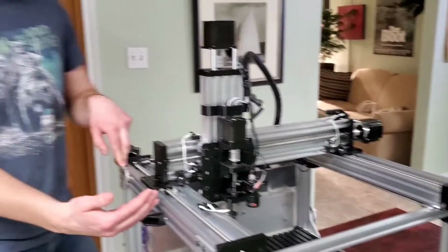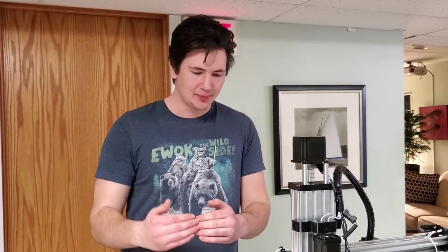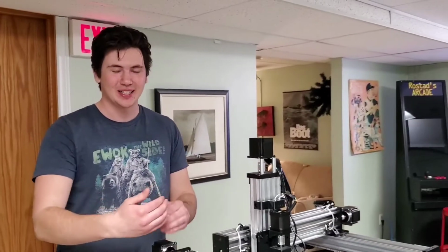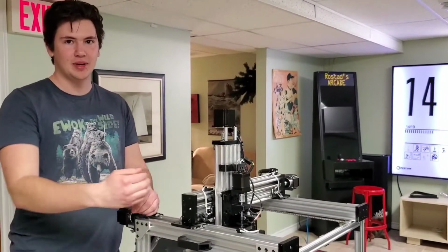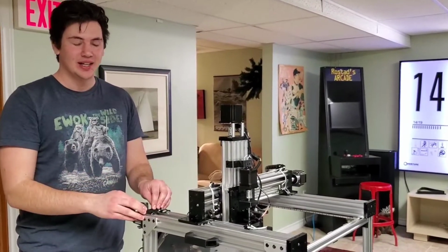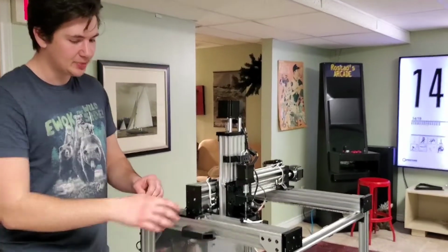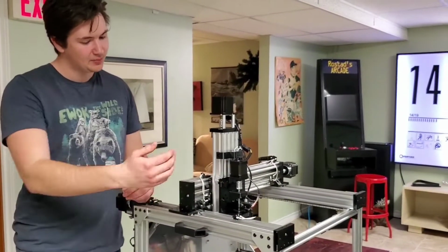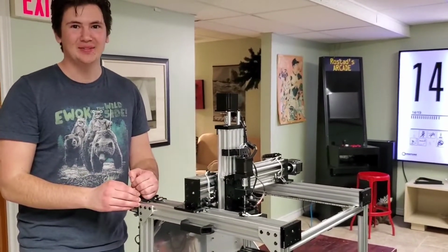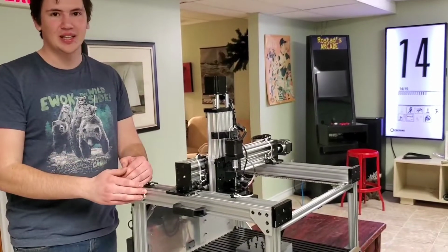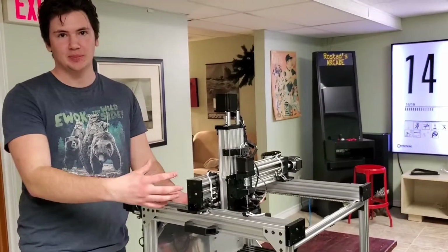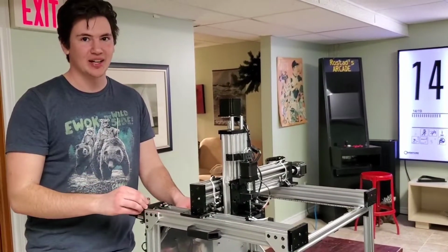As you can see, when it moves, we're not simply jerking it right up to max speed. It has an acceleration curve, and then it coasts for a certain period of time, and then it decelerates. Those are all parameters that can be changed, but we dialed it in to have close to the maximum speed that we could have. It'll accelerate, coast, and decelerate, and that makes sure that we don't skip any steps. We're not putting too much strain on the motor or any of the mechanical parts.